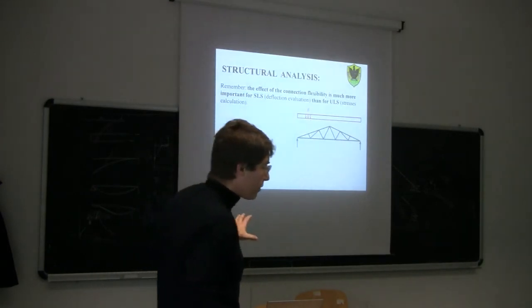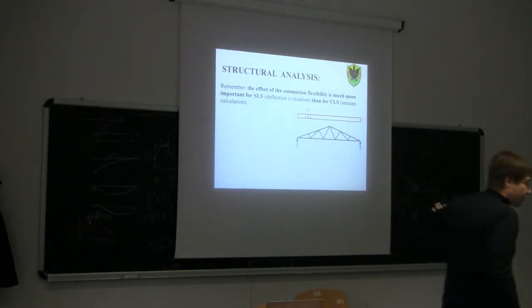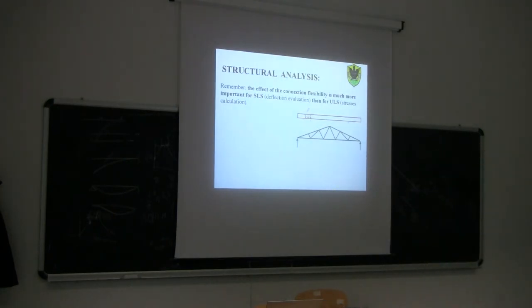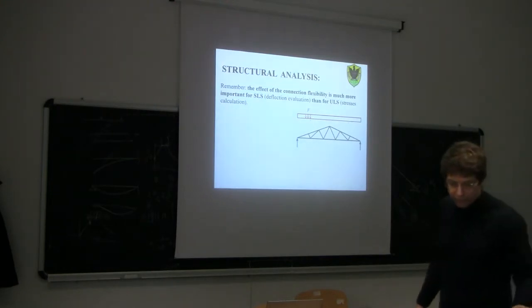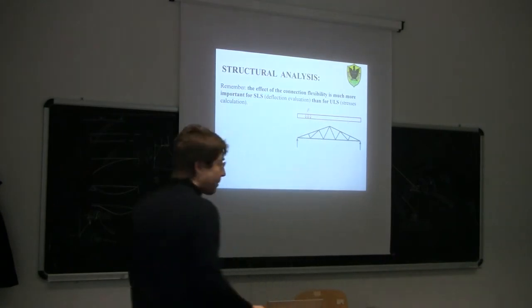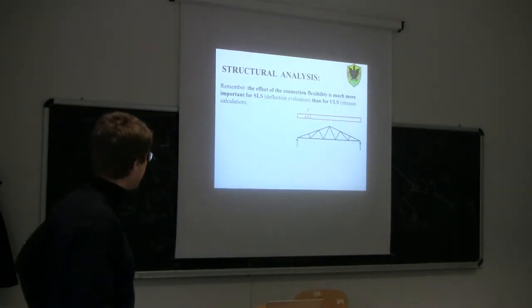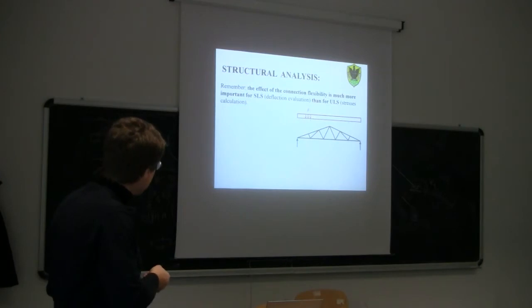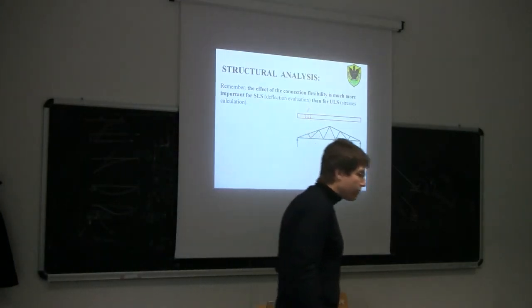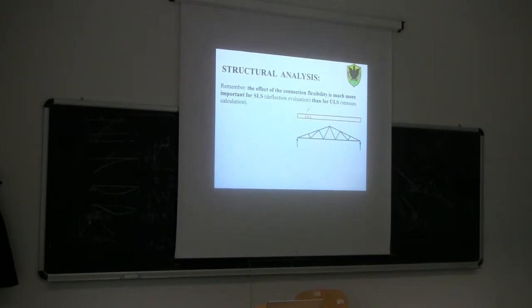I just wanted to reinforce the last slide we saw last time, which was on Thursday, about the structural analysis for a timber truss. Some of you may choose a timber truss for your project, and we saw some advice on how to do the design for a timber truss. I just wanted to remind you one important thing, that when we analyze a timber truss, we should take into account also the effect of the connection flexibility. So the fact that the connection is not rigid.